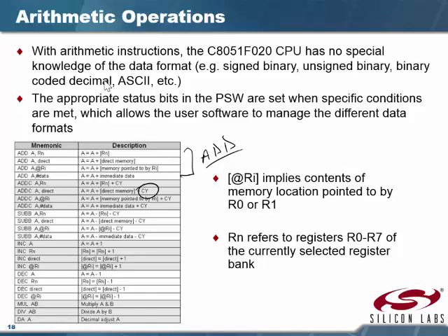We can give it a direct memory location. We can add to a memory location directly, which means that we can add to a port directly. We can look at what's on port 1 and add 1 to it and increase it. We can also place a memory address into a register and add to it as well. And everything we can add to, we can also decrement from. So we've got decrement right there.